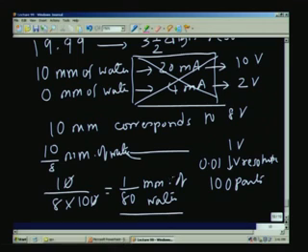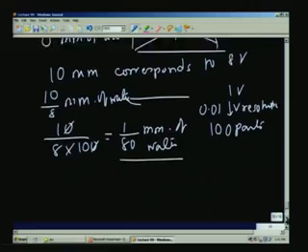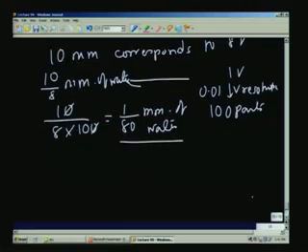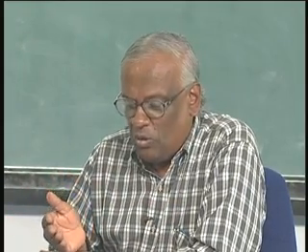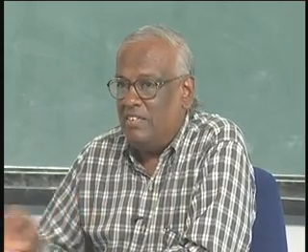So, you can now see this 1 over 80 millimeters of water column must correspond to a certain velocity change. Of course, velocity is non-linear. Velocity there goes as square, here it is going as a linear scale, because after conversion it is delta p only that I am measuring. Therefore, when I want to translate this to a certain least count in terms of velocity, I will have to work backwards and find out what this 1 over 80 millimeters of water will correspond to in terms of the velocity which is resolved. I will leave this as an example to be carried out by the student, who can work it out.